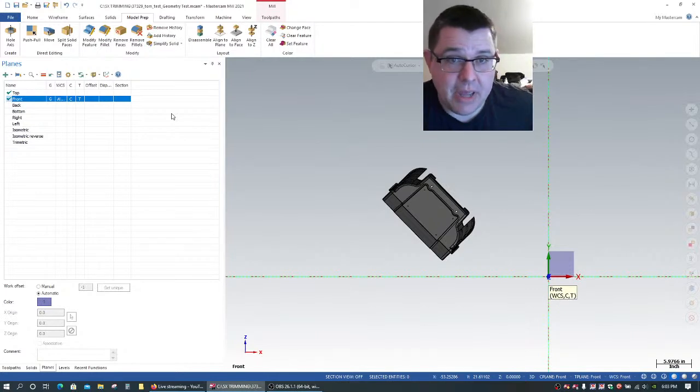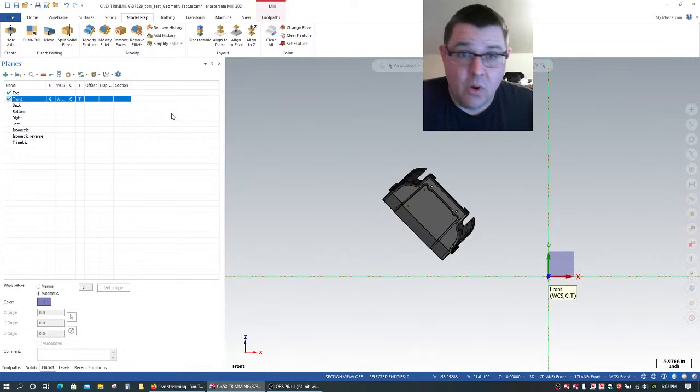So it's a big fixed bed gantry router, and the guy could be anywhere in space. We didn't know where he was going to be, so the work offset really doesn't matter in this case. It's the machine position. What we do is put the fixture on a pin. We know where all the pins are. Pins are every 10 inches: X10, X20, X30, X40, X50, there's a pin, right? We drive to a certain pin and say, okay, this is the program 0 point. We're 3 inches above 0, go. And because all the geometry is relative to an origin, everything just worked.